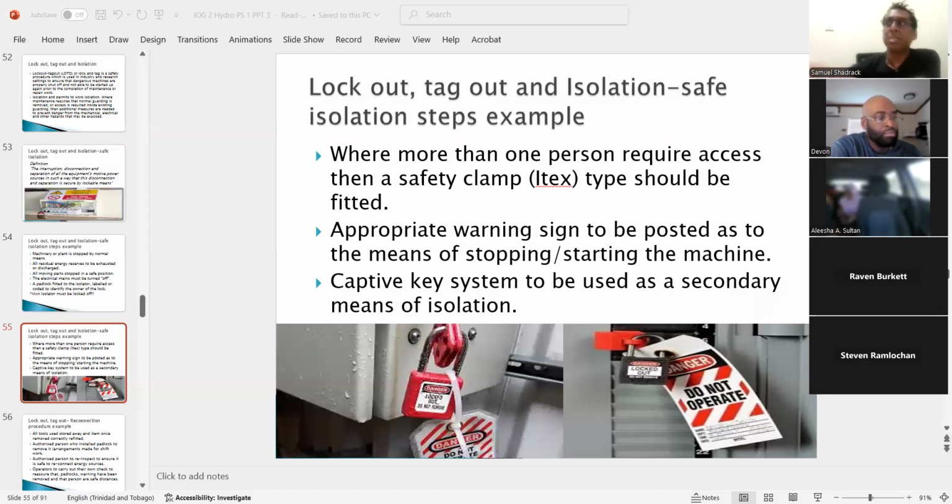What I would do is link it to an aspect of the permit to work. I would say the type of work activity is a contractor entering the tank for cleaning. This is a confined space. Then I would link it to the reason, so I can talk about proper gas testing. I'm pulling out one of the headings from the permit. I wonder if you saw what I just did. My reason why a permit must be given for tank cleaning is because, and you can pick a heading on the permit, like gas testing should have been done.